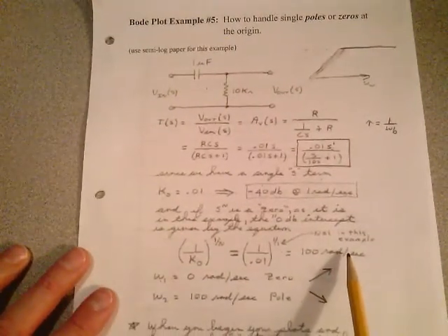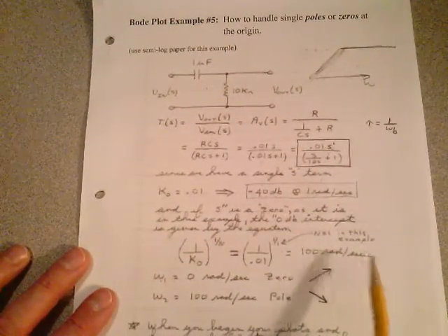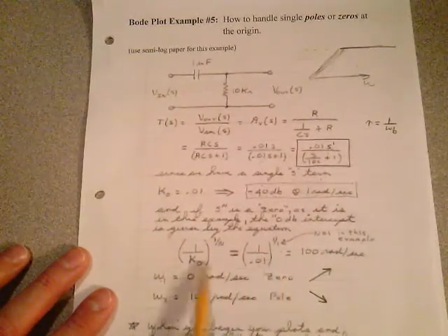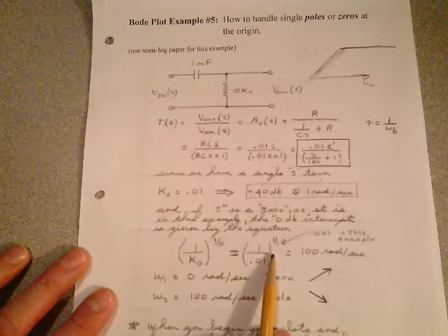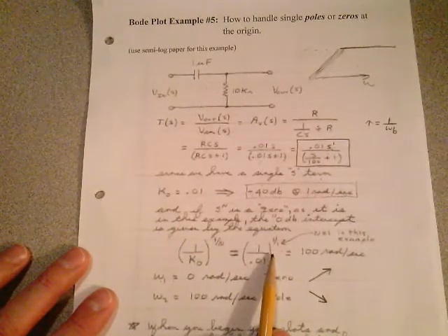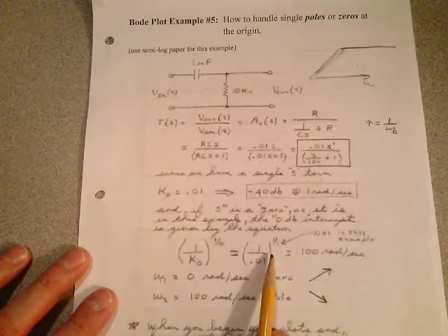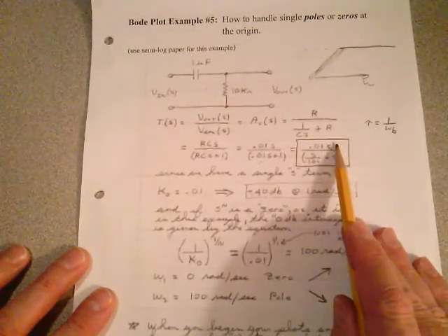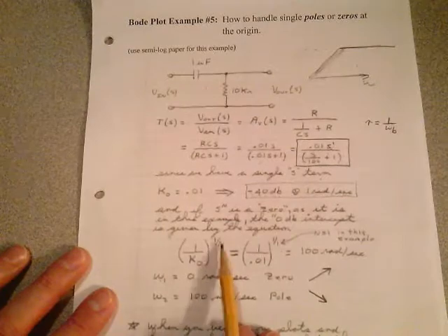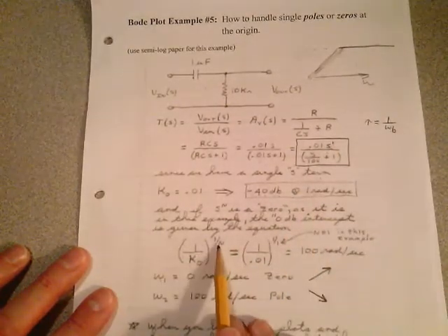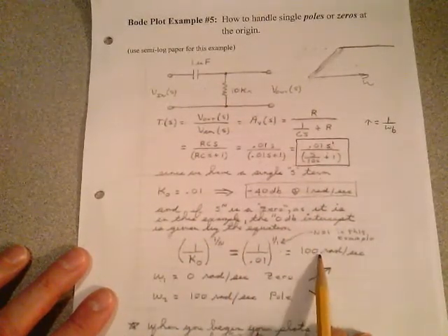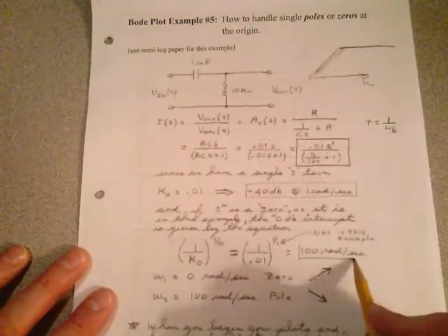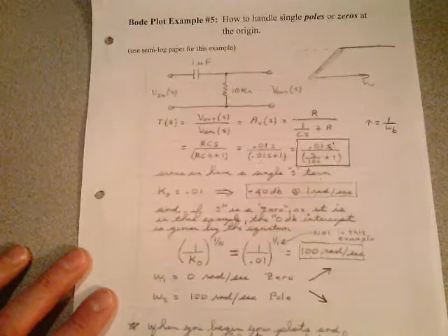Anytime you have single zeros or poles, you're going to have to go to a formula. In this case, this is the formula you use all the time if you have single zeros at the origin. And we have one of them here. If we have two of them, if that's s squared, that n becomes a 2. If it's s to the third, that n becomes a 3, and you're calculating your 0 dB intercept. So there's going to be our starting point, the 0 dB intercept.